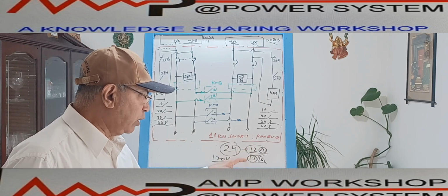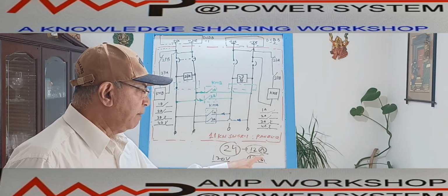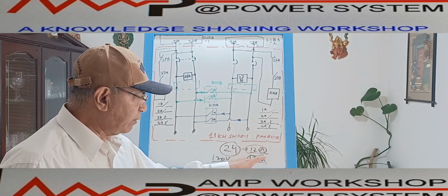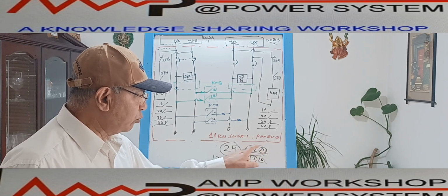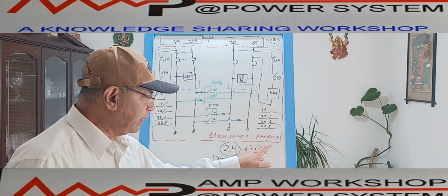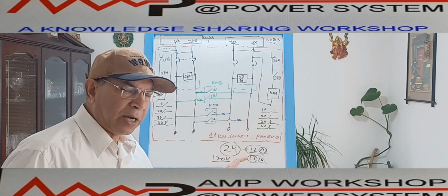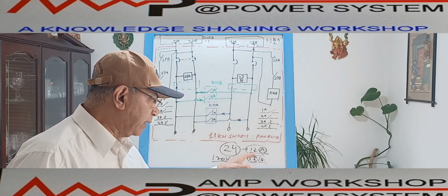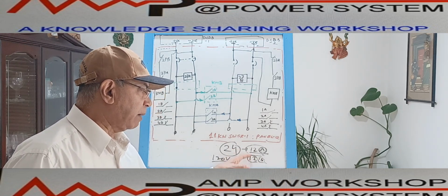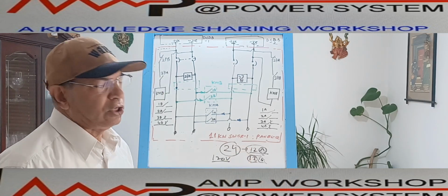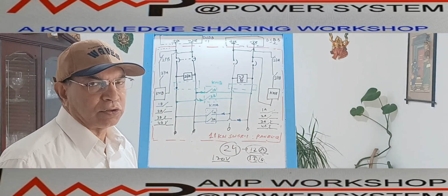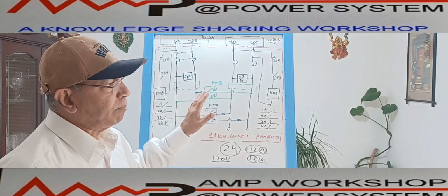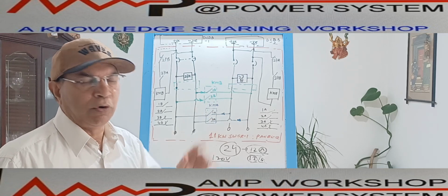That means all the 24 panels will be supplied by the B source, which is available, in case of failure of the A source. Similarly, in case of failure of the B source, the A source will cater for its own 12 panels, as well as the rest 12 panels connected to the failed power supply. The changeover scheme has to be made in such a way that in case of failure of one of the power supplies, the other power supply will cater for all the loads.